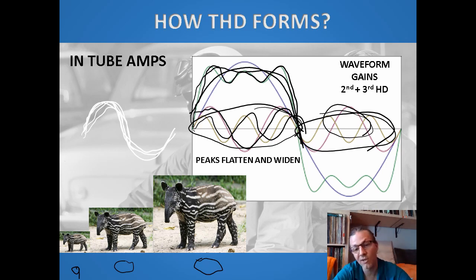And that's really critical, because when you add a second, like a third harmonic distortion, and your wave starts to become a little bit fatter, it means that the slope from the highest point dropping down to the lowest point becomes even greater. So it means that the acceleration of your cone has to be even faster. Now, if we have a typical low sensitivity speaker mated to a tube amplifier, that will make that high frequency acceleration impossible.